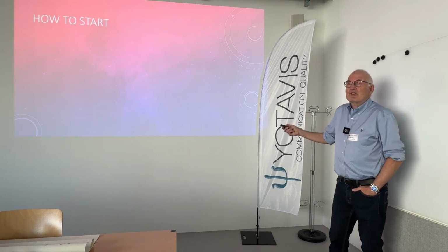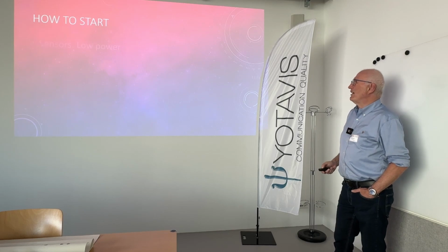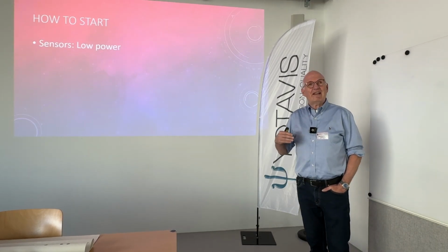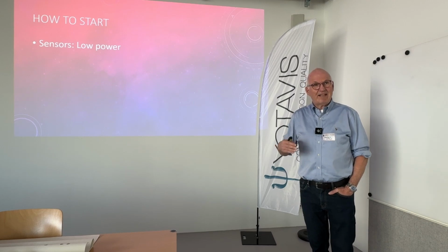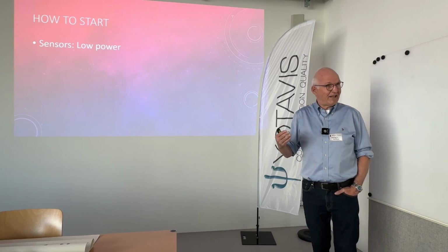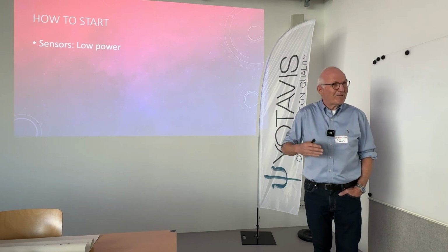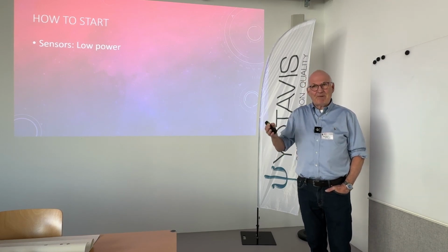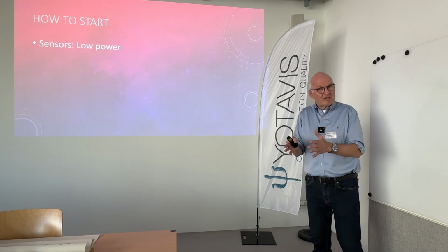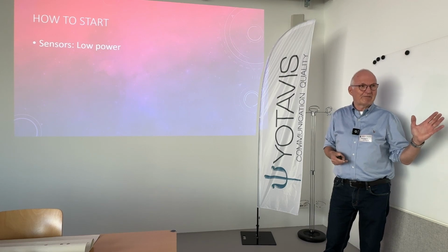So how should you start if you have nothing with LoRa? The first thing is the sensors are low power, really low power. They should work for years as a typical range. So we do not talk about microamperes. We talk about the range of nanoamperes in between the messages, because if you transmit the messages, it's 100 milliamperes.